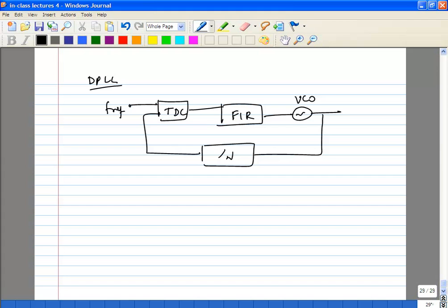So you have what is called a time to digital converter. It so happens that it is just a string of inverters and some flip flops. What you are doing is converting the delta phi here into a digital word, which carries the phase and frequency information.